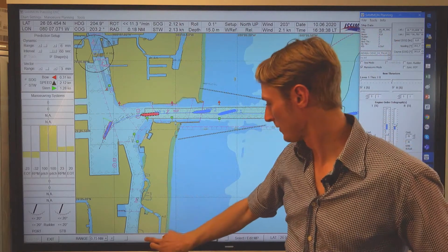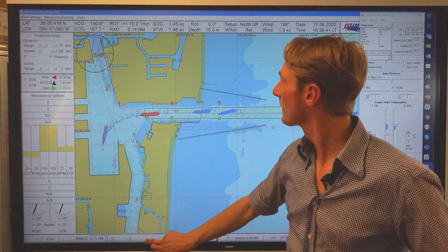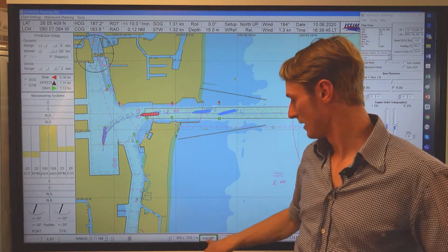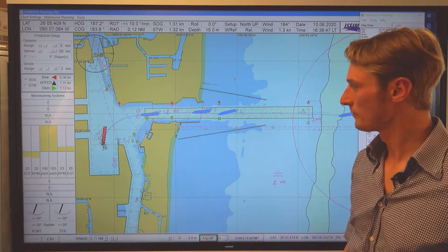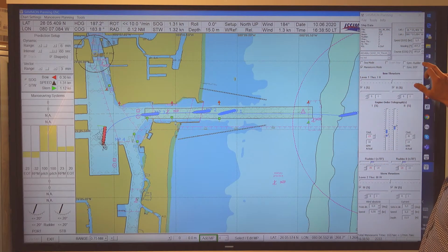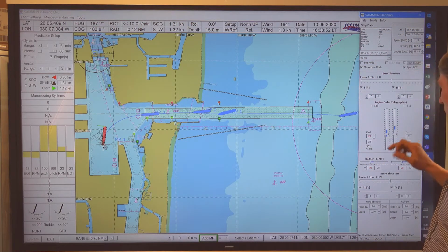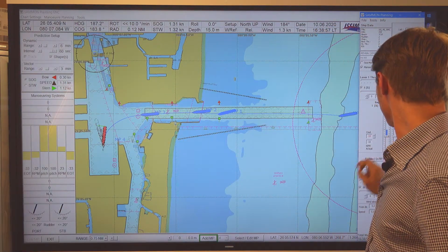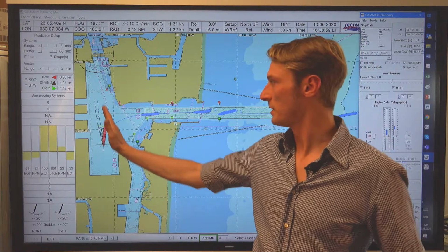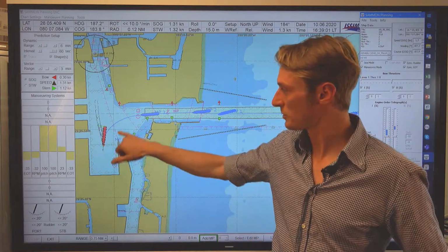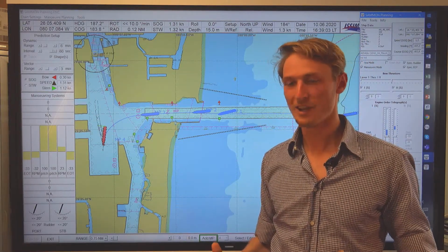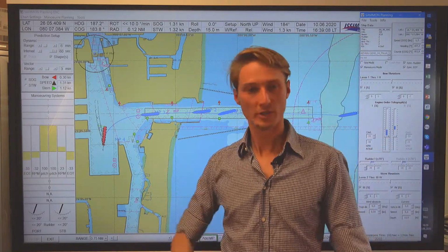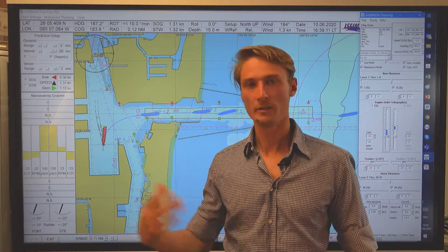2 knots. Let's move a bit further. 1 knot. Roughly 1 knot, that's a good position. Let's set a maneuver point over here and reverse both engines. Both engines running astern, slow astern, or even half astern, and I'm picking up stern speed. So basically this position is a moment where the ship is hardly moving, and I have the time to go to the starboard wing, to test my command, to control, and then proceed towards the pier.